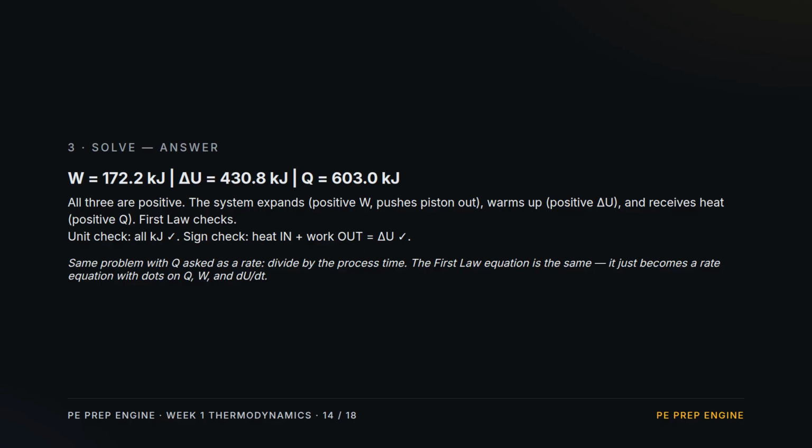Final answers. Work 172.2 kilojoules. Delta U 430.8. Q 603. All positive. The gas expands, warms up, and receives heat. First law closes. For a rate of heat addition, divide Q by the process time. Same equation with time derivatives.